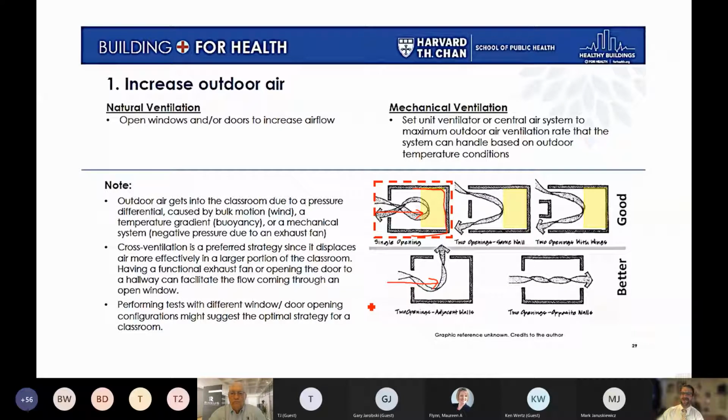And the only ways to actually scrub them out of that environment, you can do it through a cross flow, but then, and this might end up going into a hallway, so you're putting a concentrated amount of particles into the hallway. Or the most effective way to do it is to stage out air scrubbers inside the room and scrub the air within the room itself. If the air scrubbers are big enough, you may not even need to open up the windows because, quite frankly, most of the schools have enough oxygen in them that the CO2 levels just aren't rising that much.